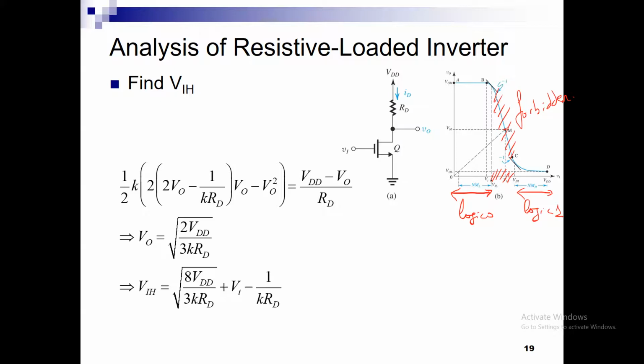And also my input signal, if you notice, this is Vn. When I want to apply Vn as function of time, I'm going to apply Vn either high or low. Okay, so I try to operate within the logic 0, or the logic 1. So I operate either at this range or at this range here. I do not operate in the forbidden region. And I hope that any noise will be within this margin. Okay, so any noise will be within this margin, for the digital operation.